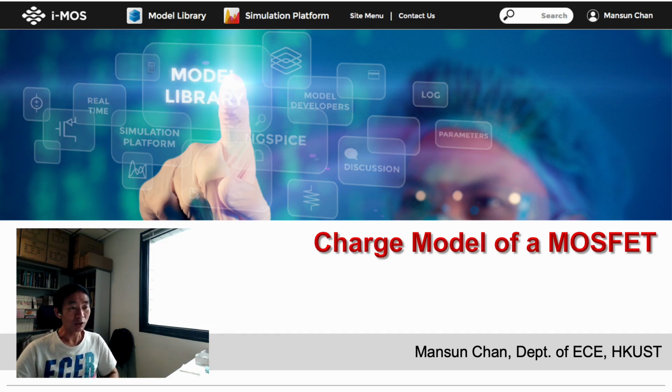When people discuss MOSFET modeling, the main focus is usually the steady-state current-voltage equation of a MOSFET. The charge-voltage model is less frequently touched upon. Therefore, I will give a more detailed example of how the simple classical MOSFET charge model is developed. Even the simplest charge model is already quite complicated compared with the basic current model.